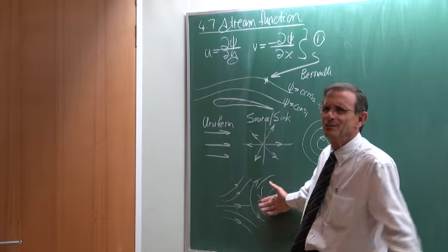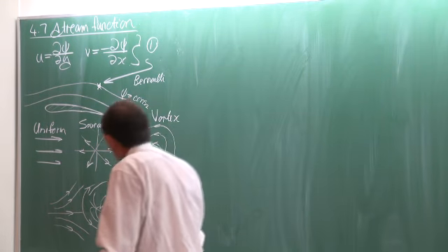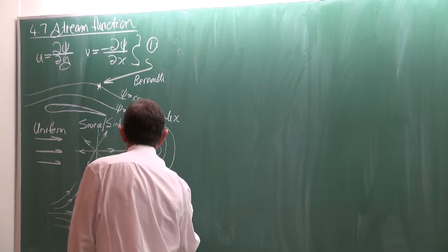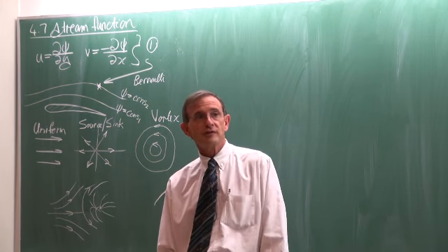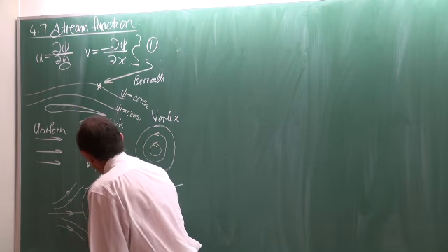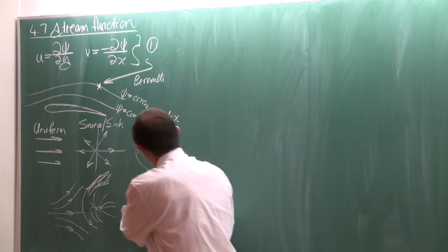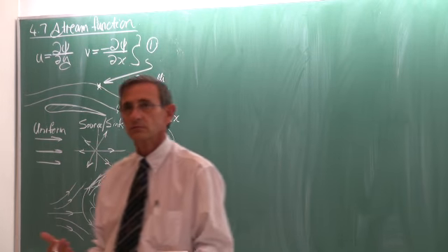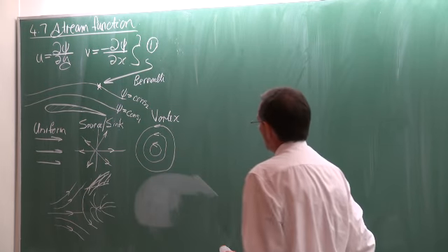Now you would look at this and say, but so what? What was the practical application? Well, many. If you were interested in the flow around, maybe the development of a new car, and the bonnet would do something like that. And if you have lots of imagination, then you can look at this and say, well, wait a minute, that part of that streamline is my geometry. And now I can go on the outside of it and determine all the velocities and the pressures. So that is typically a uniform flow field and a source and or sink.